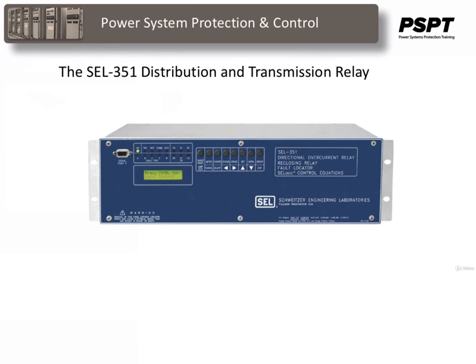Of course, the newer IEDs, intelligent electronic devices, such as this SEL 351 distribution and transmission relay, get rid of the need for old school trickery by using solid state magic. The SEL 351 protection relay is a microprocessor based distribution feeder protection management system. They call it a management system because it does a whole lot more things than just look after the overcurrent and directional overcurrent protection for the line.